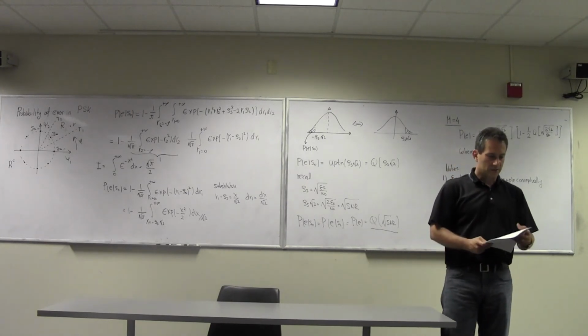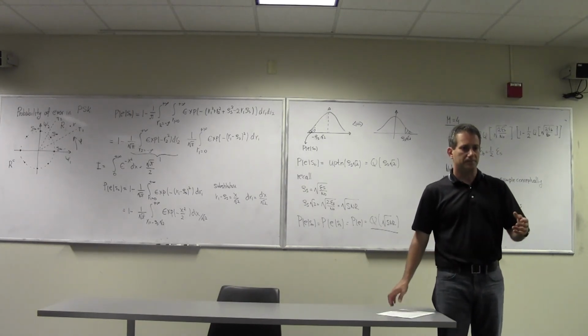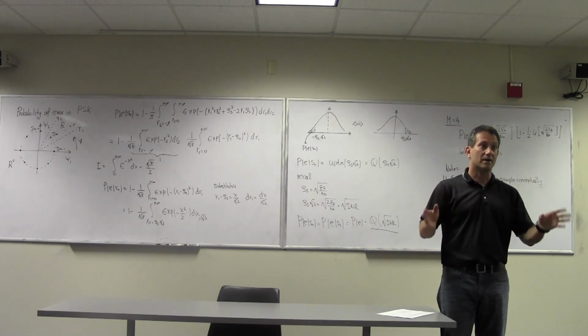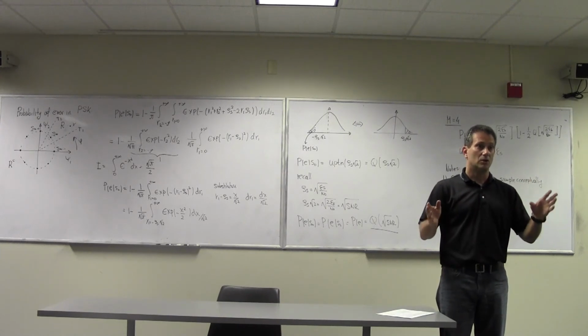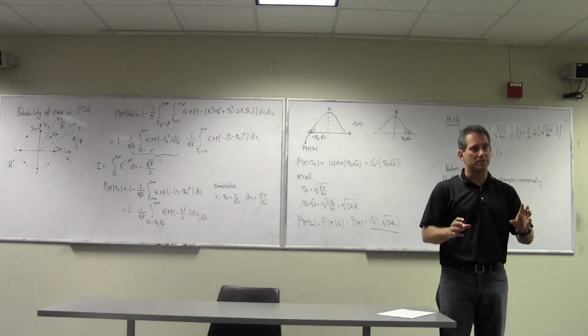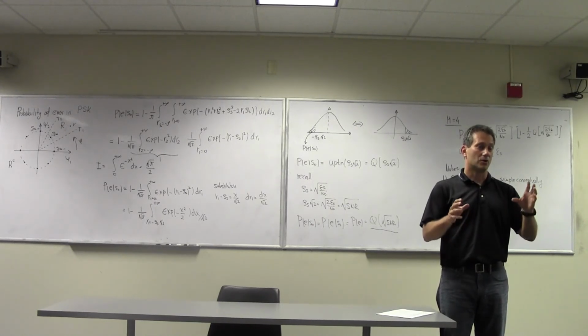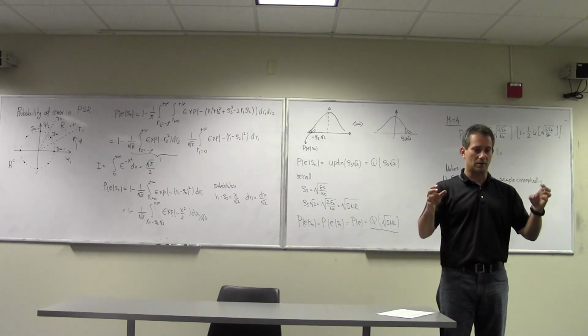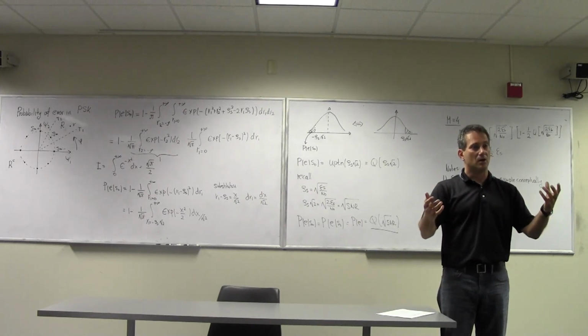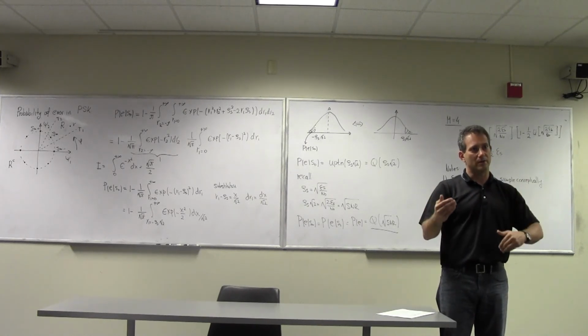The question is, when you're doing your link budget, if you switch to a higher level modulation scheme, meaning you're gaining some throughput, right? Because every symbol now carries more bits. You have to pay. And how do you pay most commonly? In power, right? So whenever you switch from a lower modulation scheme to a higher level modulation scheme, you have to increase the power. Now, things usually go the other way around.